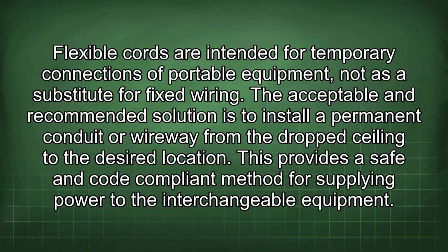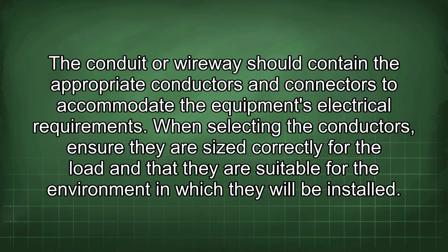The acceptable and recommended solution is to install a permanent conduit or wireway from the drop ceiling to the desired location. This provides a safe and code-compliant method for supplying power to the interchangeable equipment. The conduit or wireway should contain the appropriate conductors and connectors to accommodate the equipment's electrical requirements.